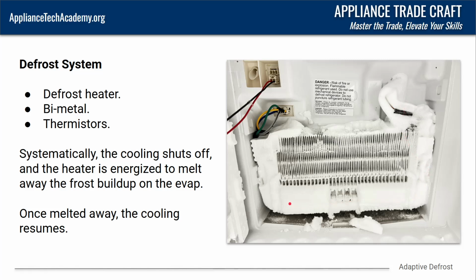But you can see we've got a clear defrost issue here. Now, typically, you're not really going to be able to see it here, but generally you're probably going to have the bimetal over here. The wires come in for the heater, come up over there. And then that's probably, if I were to wager a guess, going to the evaporator fan. Kind of getting off track there, but basic defrost system right there for you.